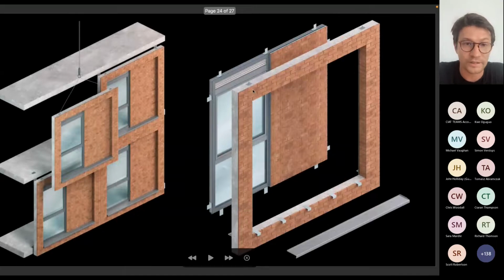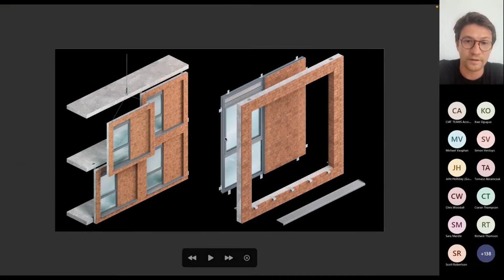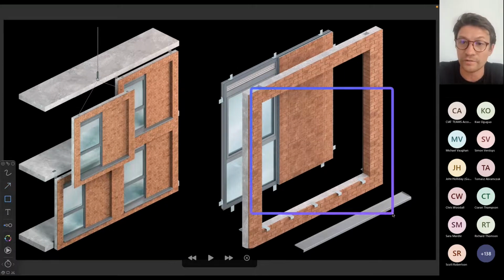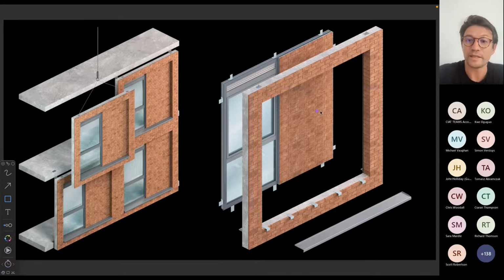So here is your donut, and as I said previously, a precast donut that receives the window, and it requires some amount of, as I called it, meat to achieve the structural integrity and to be able to be craned into position. In our case, it is 1.5 bricks here and 4 bricks in height. And this pretty much is virtually the minimum you can do in brick and precast. But we need to get the recess here, and that is flush with the window, hypothetically.